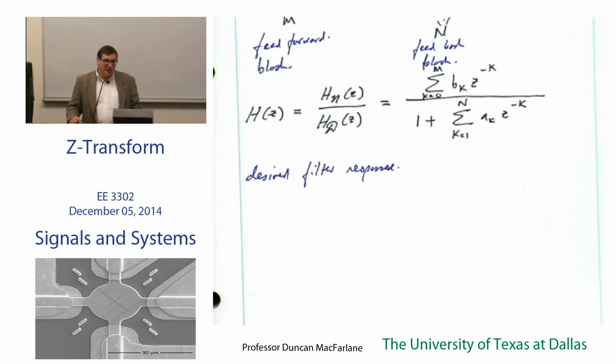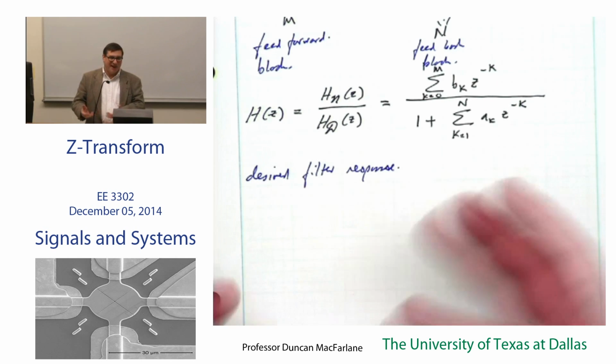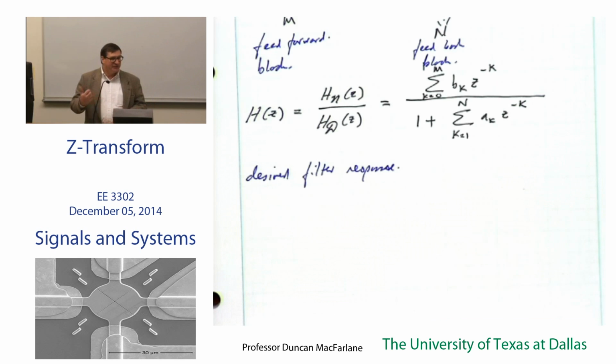What you do is you come up with algorithms for doing those fits, those splines. And there's not one algorithm, there's a variety of them, and some work better than others in certain situations. And they're all stored in MATLAB. So MATLAB is a repository of 25, 30 years of this curve fitting work that helps you design filters exactly this way. FIRs versus IIRs, and so on.